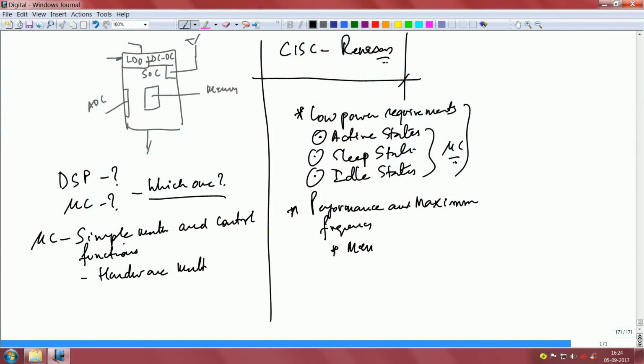I showed you that picture of a load store where memory copy happened in two different ways. The RX MCU did it in just memory copy and the other one put it to a temporary register and pulled it out. Number of clock cycles are more, it is doing a simple operation, there is a load, there is a store operation involved. So, the architecture plays a huge role in the whole process. Then we also mentioned that the process technology becomes important from a performance perspective. Then memory technology.